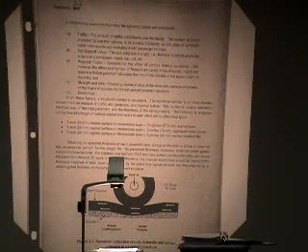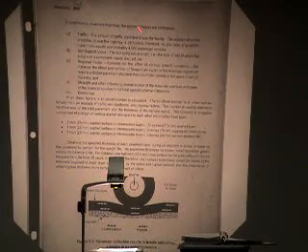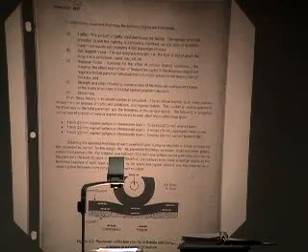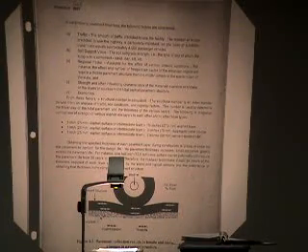Now, obviously, the total number of vehicles that you'll have using a section of roadway determines whether you need 2 lanes, 4 lanes, 6 lanes, or whatever. But it's the trucks that really drive how thick that pavement needs to be. If you notice here, it says 1 loaded tractor trailer equals approximately 4,000 passenger vehicles from a pavement design standpoint. So it's really the trucks and types of trucks that makes it different.